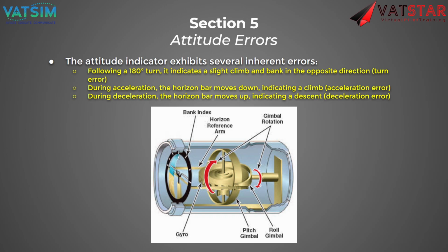May I add on that? Sure. There's also the fact that your angle of attack might affect whether it's showing climbing or flying straight too, depending on different speeds. What do you mean? In certain situations, the nose of the plane might not be aligned with the direction that you're going when you're flying a high angle of attack. Oh, sure, but that doesn't make the instrument inaccurate.